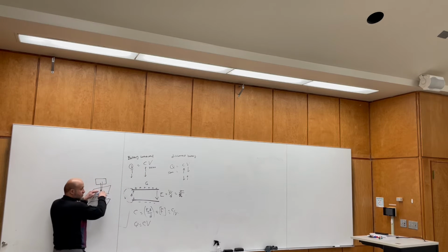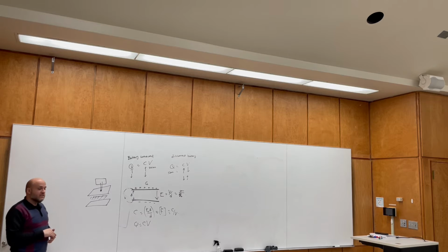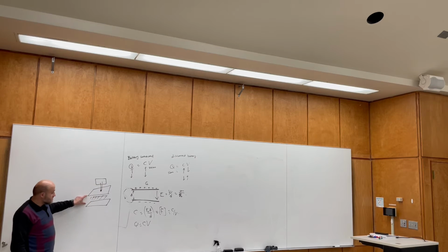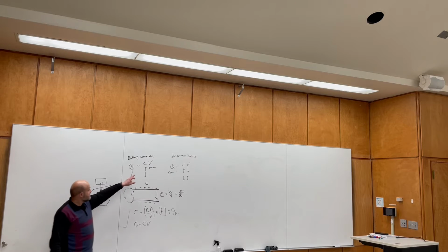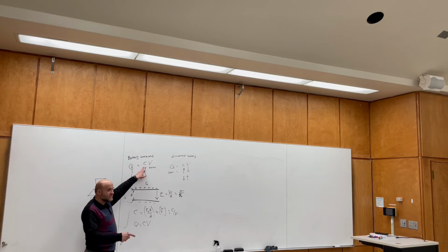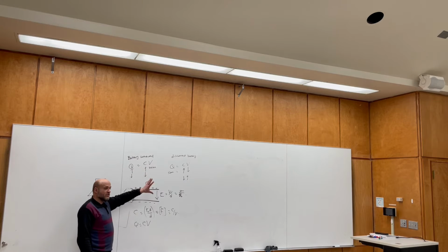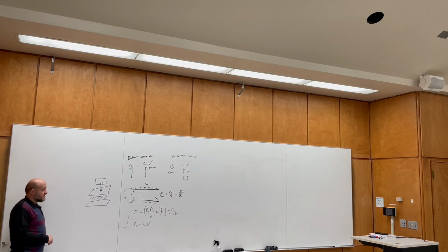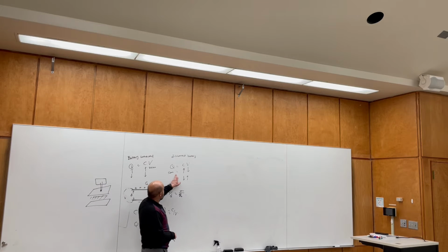So there's more charge on this coming from the voltage, and this is attached to create a charge signal, and this signal can go to another circuit to analyze it, consistent with the key you pressed. Each key has a different distance between the two plates, a different D, and a different D makes a different C, and that C is specific to each key. For each key we have a different C and a different signal. So this is one application for capacitors. For the case when we have Q constant, they make microphones.